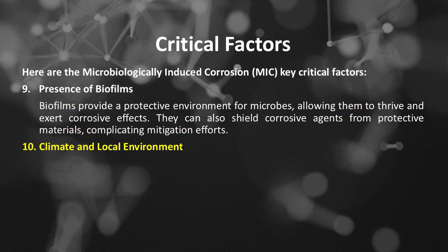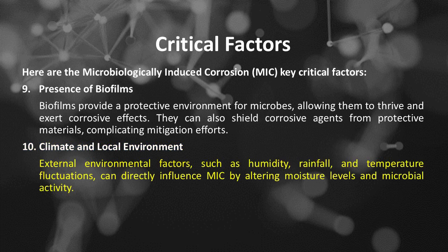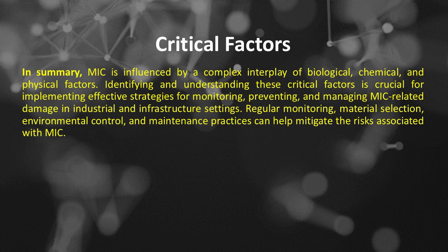Number 10 of the microbiologically induced corrosion, or MIC, key critical factors is climate and local environment. External environmental factors, such as humidity, rainfall, and temperature fluctuations, can directly influence MIC by altering moisture levels and microbial activity. In summary, MIC is influenced by a complex interplay of biological, chemical, and physical factors.